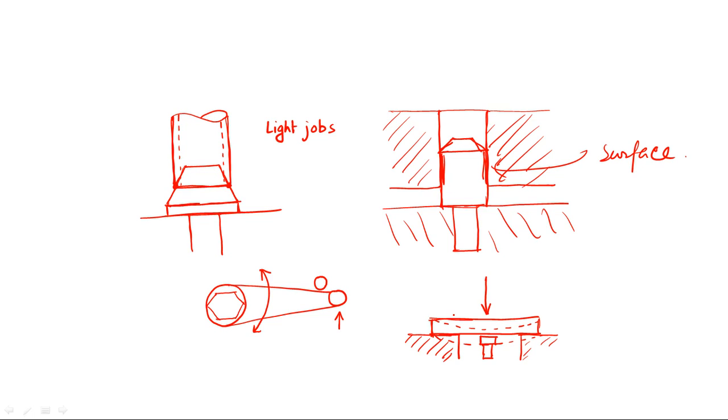As I told you, the clamping force should act against a rigid part of the job, so that it will not damage the job. Now, the material of the clamping device and the locating and supporting devices must be wear resistant, so that it will not fail easily.